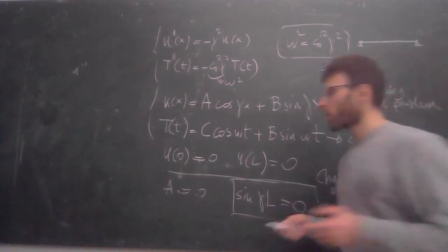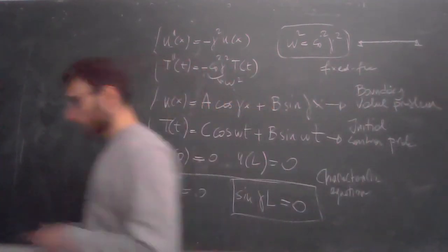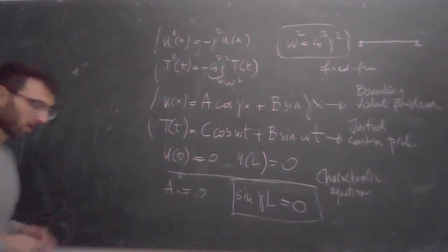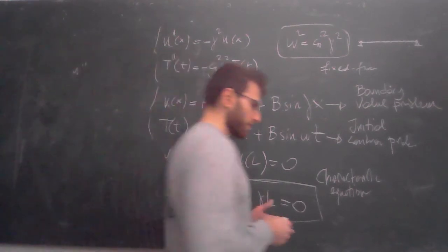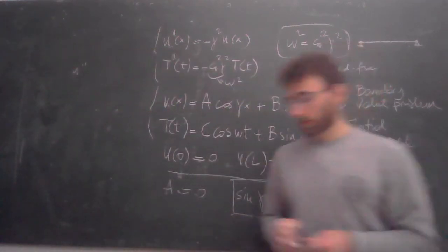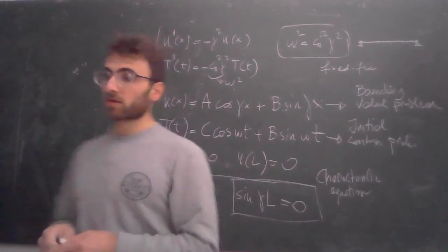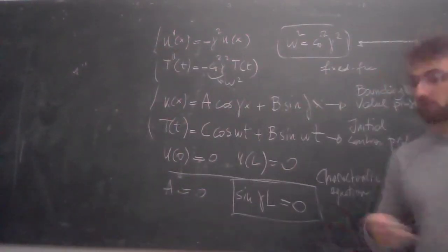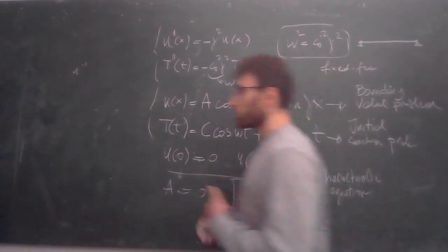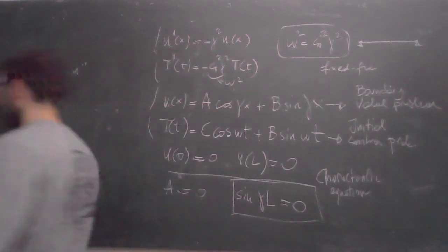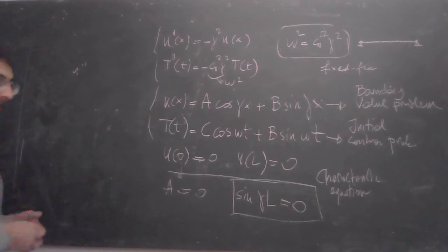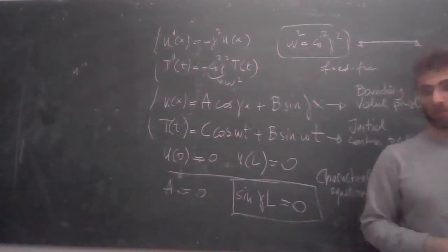For instance, you saw with the other professors in the first part of the course that if you want to solve the discrete dynamic equations, you have to set to 0 the determinant of the mass and stiffness matrix, and then the determinant equal to 0 is the characteristic equation.